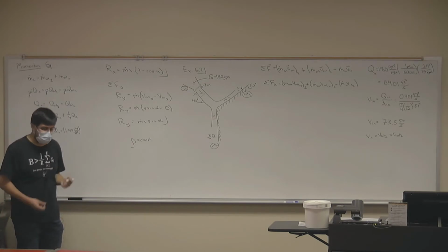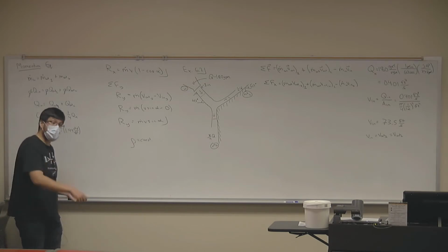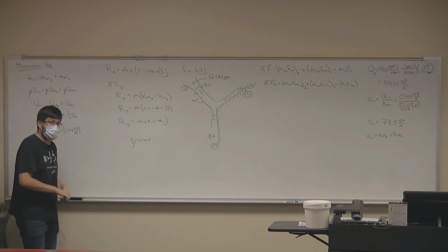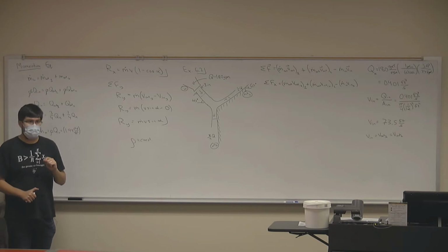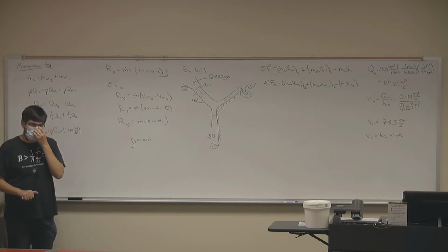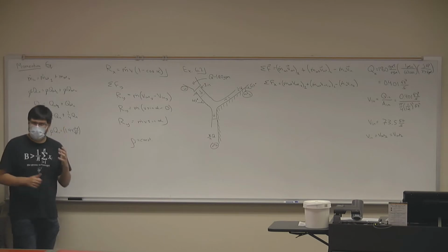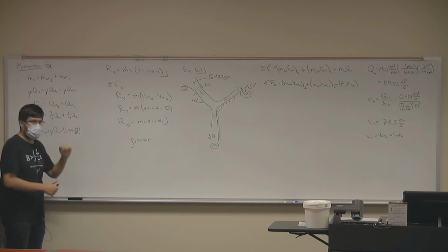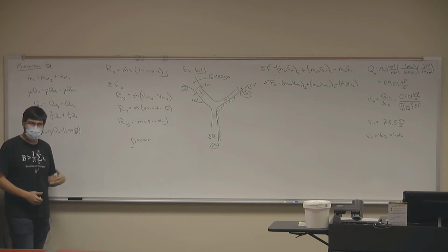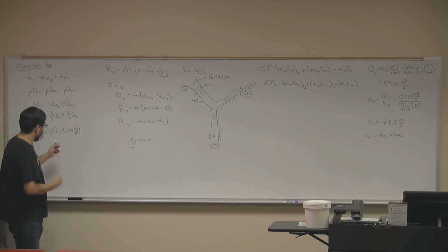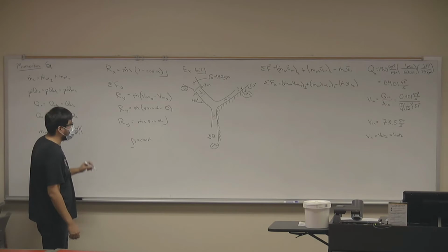All right, Andy, let's say that you forgot the density. You don't have your notes, right? And you lost your tables. You forgot the density, but you know that the specific weight is 62.4, right? How can you go from that to the density? Divide by the gravity. Exactly, right? So if you forget the density, but you know the specific weight, just divide it by the gravity, and you'll get 1.94. So divide 62.4 by 32.2, and you'll get 1.94. So it's good that you mentioned it, because it's always good to be able to relate all these properties. So 1.94 slugs per cubic feet